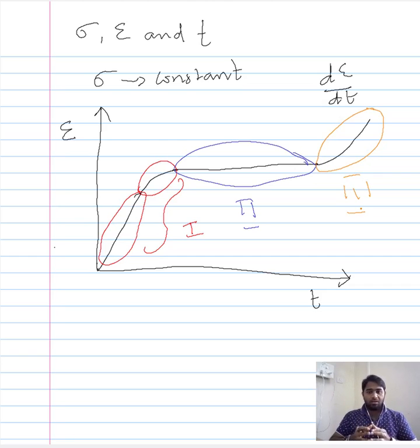Meaning, so far what we have done is we have just coupled the first two aspects of the creep curve, which have different slopes, into stage 1, and the second section of the creep curve, which has its own characteristic slope, as stage 2, and the third section of the creep curve, which adopts a different trend, as stage 3. Now, this is just one of the ways of categorizing and distinguishing the creep curve.